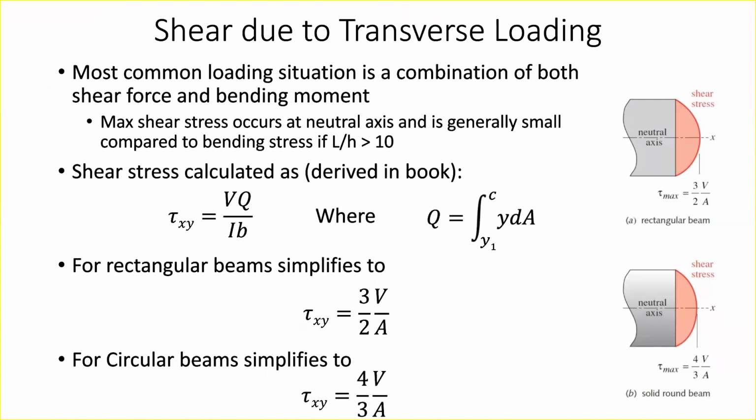This is just another effect from the bending. If I were to bend my phone, I have that normal stress that we were talking about before, but there's also an effect where there are slight shear loads across the plane of the part as well. I'll link the Shigley's book, and it divides it up into these different sections of loading. So if you ever recognize a certain phenomenon is going on, you go and reference the book and look up the formula. And it is typically still much more efficient for understanding the problem than doing an FEA.